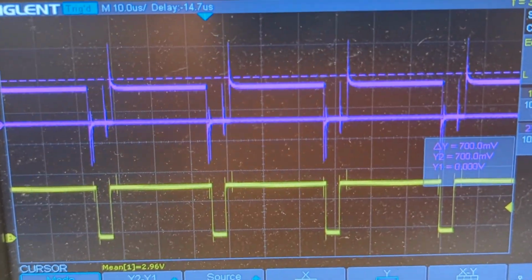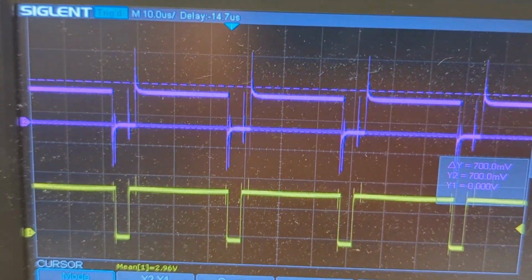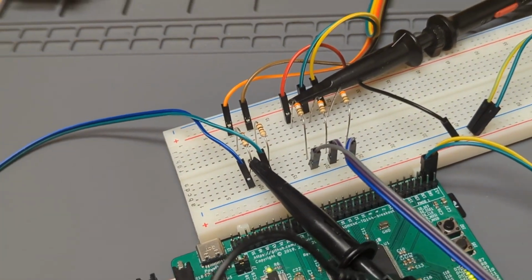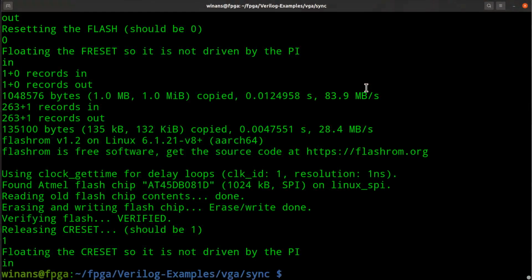But the beauty is the video doesn't show any problem. Usually, if the overshoot is really bad, you'd see a real bright or a weird rolling black haze on the left edge of a brightness transition. And I'm not seeing that on that monitor. So in spite of this outrageously noisy signal here, which will probably go away if I etched a board and got rid of all these wires, the video's looking really good.